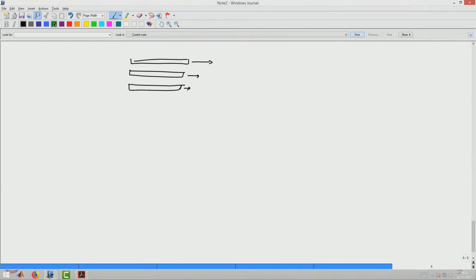All of these are balancing each other by having a set of stresses, and what we are saying is all of these stresses are constant. Each layer exchanges the shear stress with the other layer, and the value of the stress does not change as we travel in the y direction. This is based on the linear momentum balance for a simple shear flow in a rectangular coordinate system.